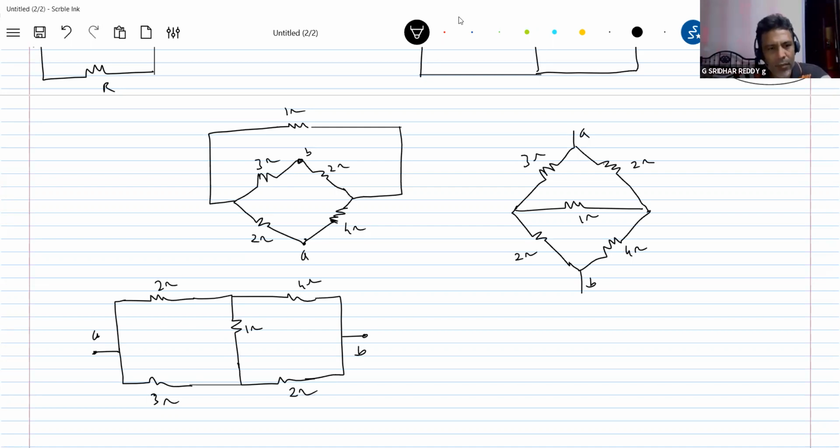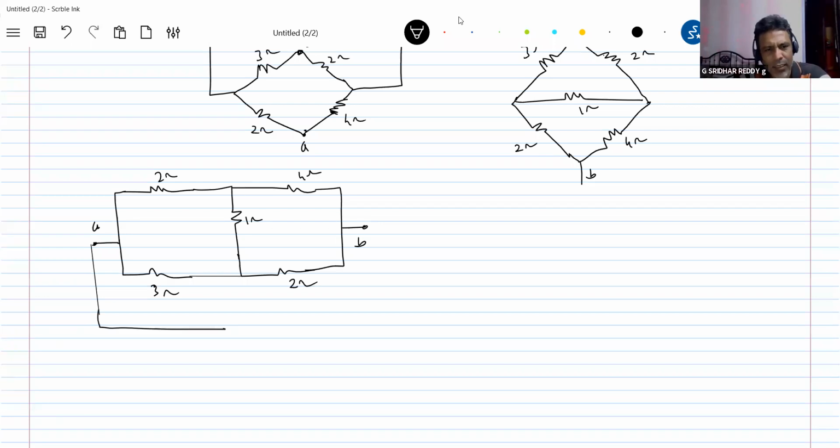I'll ask you to bring a cell, some voltage, to get the answer. You're bringing it just to get the particular effective resistance RAB. So here I'll bring some V naught. This is to make the problem simple. Let me bring 2 volt. So a current I will flow. This cell will see the effective resistance RAB, the total.